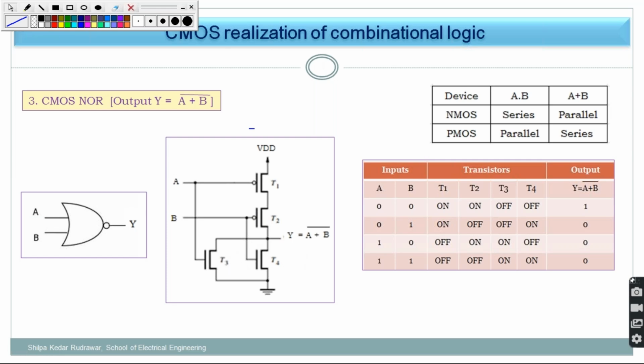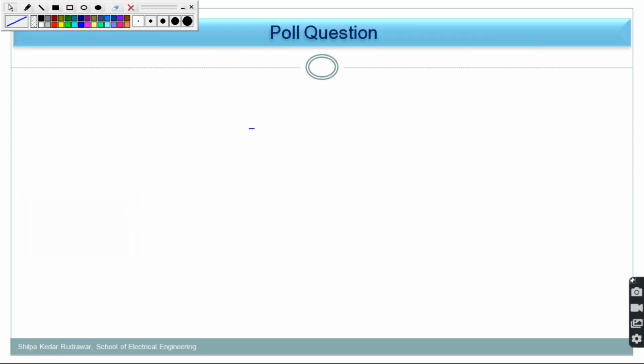So in the Microwind practical, whatever you need to perform related to VLSI, you need to implement an inverter, a 3 variable NAND gate and a 3 variable NOR gate. So just draw on your own on paper that 3 variable NAND and NOR gate. It will be easy for you to implement using Microwind. How to implement using Microwind, I will tell you afterward, because this session is not related to practical.